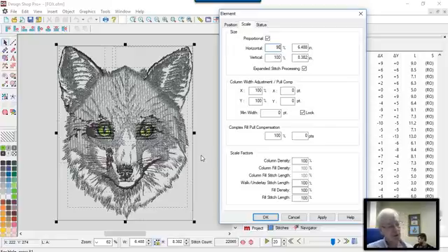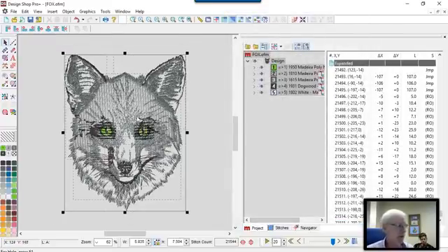And there's, of course, as we've spoken before, I could convert this to wireframe, but when you do that, you're really reverse engineering a lot, and you're going to get a little distortion each time you do it. A second way to convert to wireframe is not to convert the entire design, but just to convert the part you need to work on. All right, so scaling, I think we've explained: set it to 90, hit it, and it's going to scale 10% down.